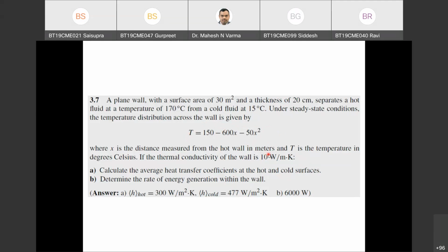I can say thermal conductivity of copper, of a plane wall, of water, of air, but I cannot say heat transfer coefficient of water or of air. It is a property of the system; the whole system I need to define, and based on that only I can judge the heat transfer coefficient.